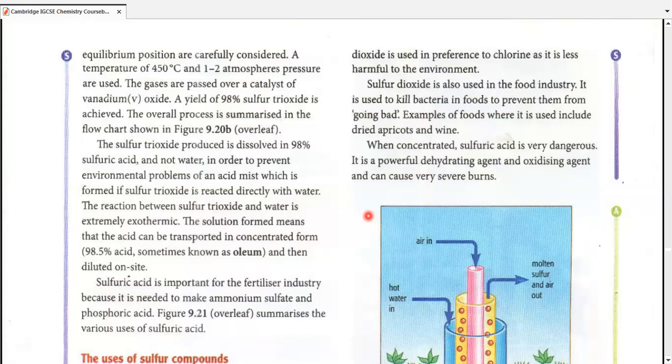This reaction, sulfur trioxide reacting with water, was a highly exothermic reaction. The sulfuric acid produced was quickly evaporated and converted into vapor form, tiny droplets. Those droplets still had that acidic effect. We called it mist, but acidic mist. That acidic mist was a big problem. Why? If it was contained inside any material, it was so corrosive, sulfuric acid being one of the best acids of the world, it slowly ate any material that covered around it.